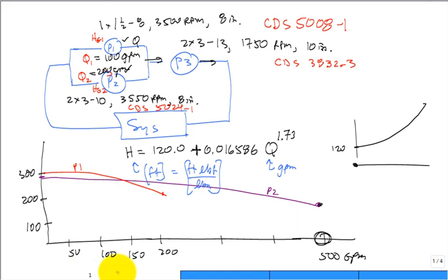We're going to do this in a computer code, but I want to do it by hand first. What did we have? We had a head gain of 285 and 285. And then what about the head gain for pump 3? 85. So we have 285 plus 85. What do you get for the net head gain? 370. Okay. So guess what has to be the loss across the system? 370.